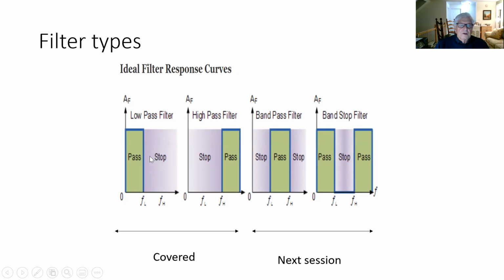In the case here for a low pass filter, we can have a low-pass filter if we output from the resistor of an RL circuit, okay? Or we can have a low-pass filter if we output from the capacitor of an RC circuit, and vice versa here for our high pass.